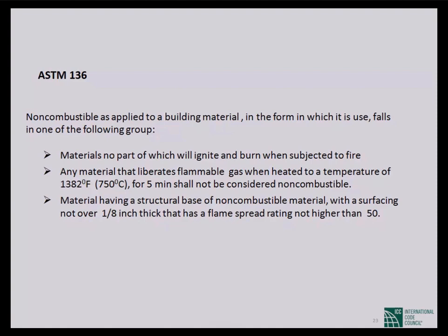First thing is material, no part of which will ignite and burn when subject to fire. So there will be some fire, it will not ignite or burn. Second thing is, if the material is a composite, and actually now we are using a lot of composite. If the base material is non-combustible, if it is coated with something flammable, if it is heated up to 750 degrees centigrade, if it is allowed for 5 minutes, the vapor it will liberate. If it is not flammable, then it is non-combustible.